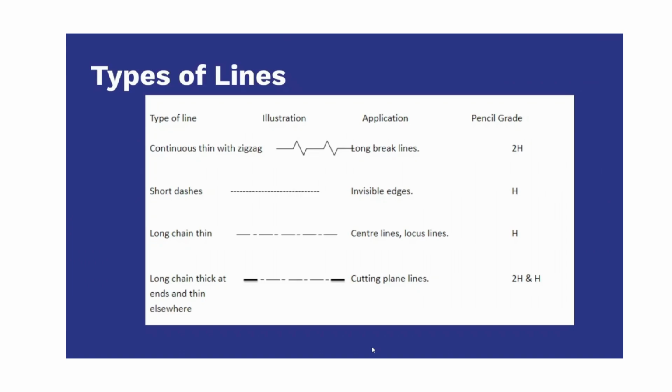So kindly keep this in your mind, guys. We are using long break lines here, and the pencil grade is 2H. Okay, this is the continuous thin line with zigzag.